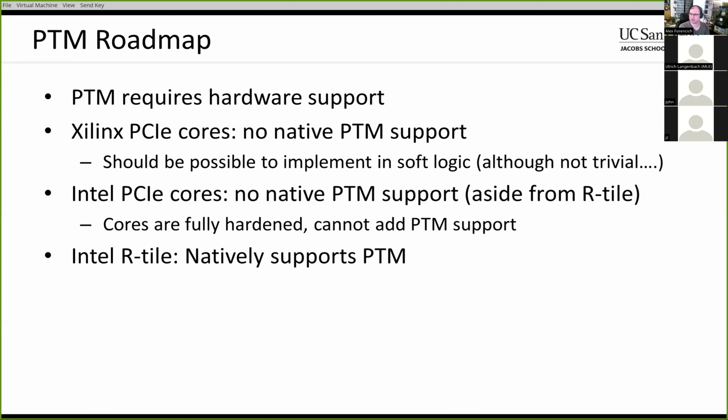But I think that should be possible because in all the Xilinx devices, at least setting aside some of the Versal CPM stuff, where it is all done in hard logic, you do have access potentially to the connections between the serializers and the PCI Express hard IP core. So somewhere in there, it should be possible to get access to the TLPs and do what needs to be done for PTM to work.